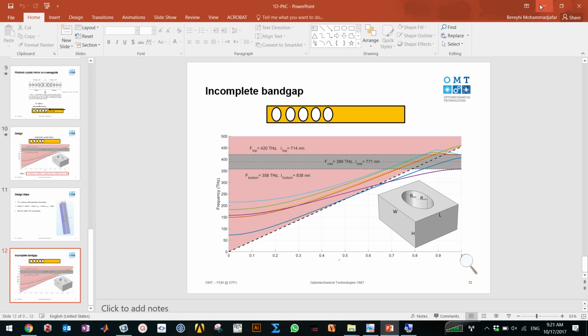So yeah, I don't want to simulate the whole region, the whole area possible. If you do that, you will get the result. But I just want to make my model a bit smaller. So I just, for example, extend the dimension of this air box like 5 times, 10 times larger than my active structure, and then I will say, okay, this is PEC, so this is when your field is 0. I don't want to go further than that.